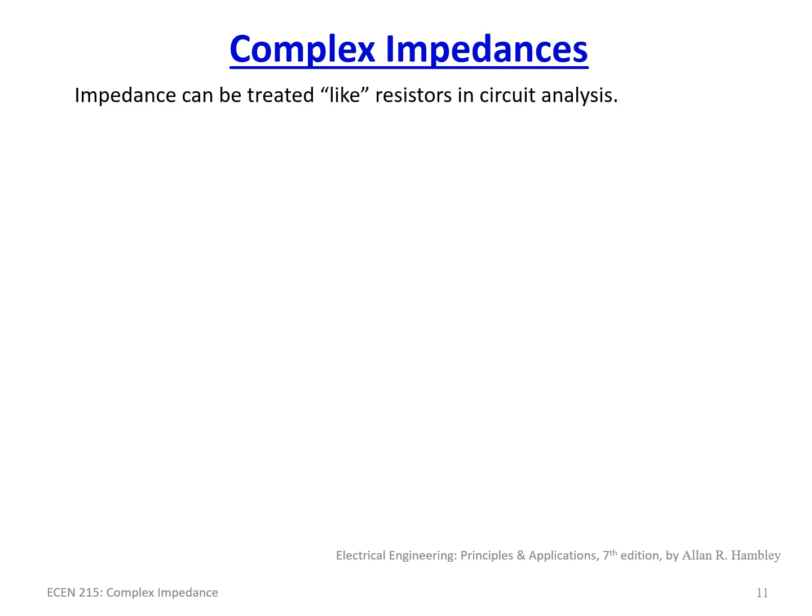So complex impedances can be completely treated like a resistor in your circuit analysis, meaning that you can add all the impedances in series. You can replace all of your resistors, capacitors, and inductors, the actual elements, with little round or square boxes, change it to Z's instead, to an impedance value, and then you treat it like you would a resistor.